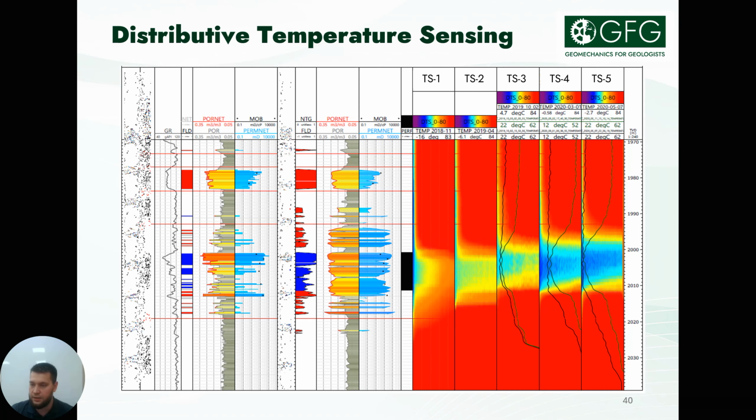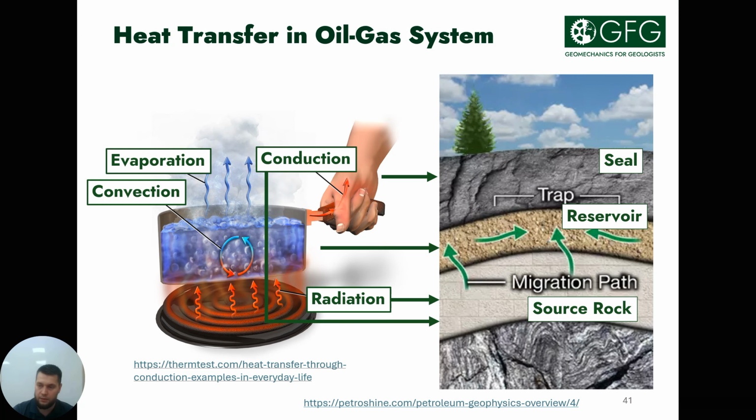Distributed temperature sensing is one of the best seal integrity monitoring methods, and temperature anomalies make it possible to identify the limits of fracture propagation of an injection well and prevent fracture breakthrough in the overlying and downstream intervals.